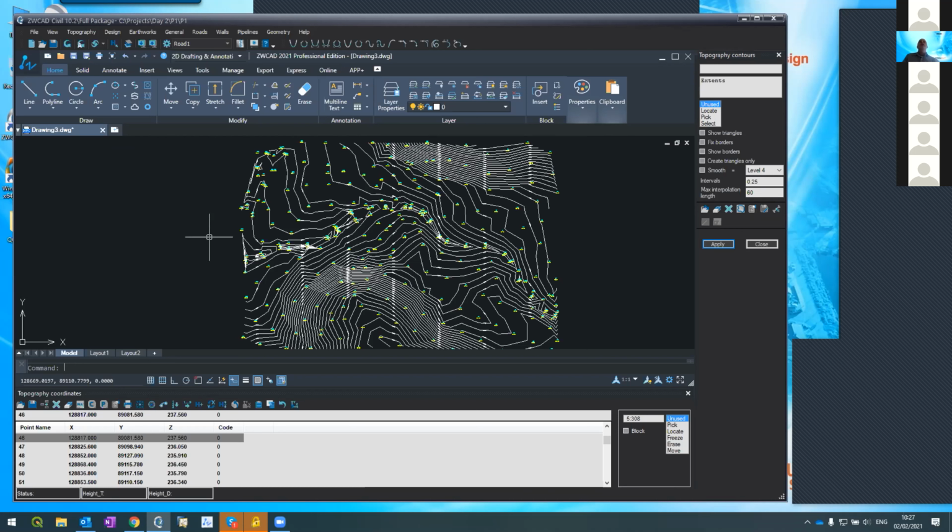Look, a surveyor in a terrain which doesn't have many changes will use 60 or even 100 meters. If there are a lot of changes, he will put a lot of points. So it depends on the survey data that we see. We can play with it. I usually start by 60. I look at my borders to see if there are problems. Then I can play with it. Thank you.